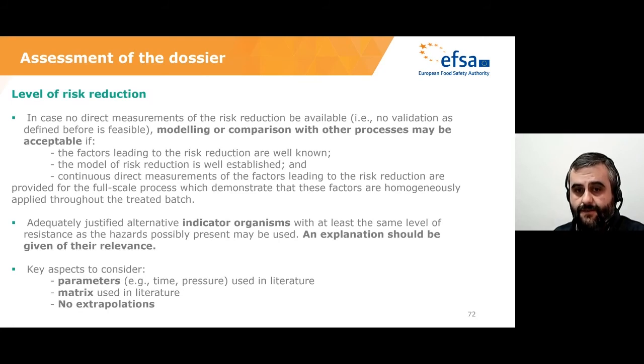First, the factors leading to the log reduction should be very well known. So if it's a thermal process or a chemical process, it should be very well known what the effect of the heat on the hazards is. And there should be good models or good literature showing the effect of that factor, so let's say the temperature, the pH, or whatever, on the hazards that are important in that material.